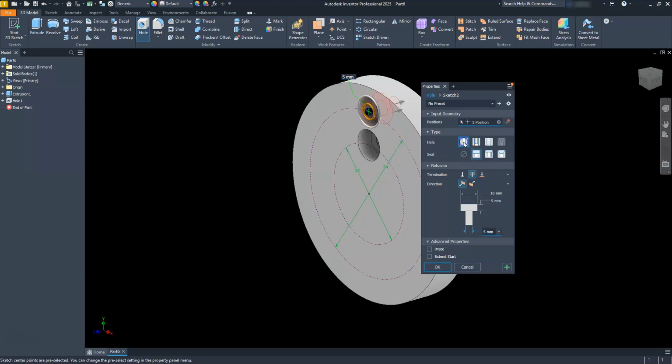I'm just going to make this one a simple circle. It's just cut right through. There's no complicated parts in it. So I'll select that icon there. I have no seat on this one, so I'm just going to unselect it here. And then I have to specify what the diameter is, which is going to be 8.6. Right? And so once all that information is satisfied, I'm going to click this plus icon.